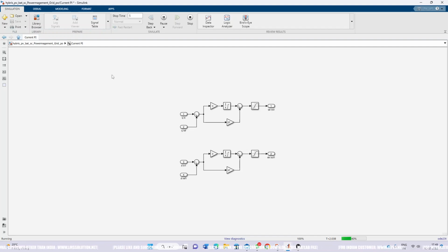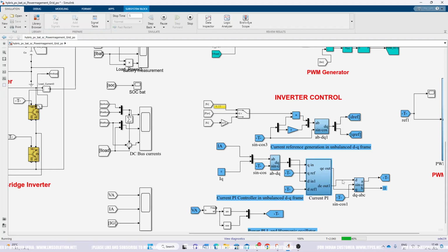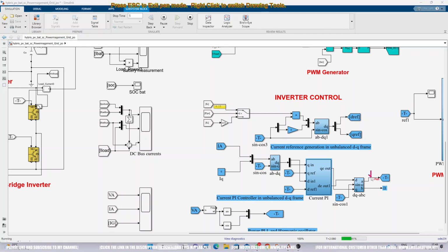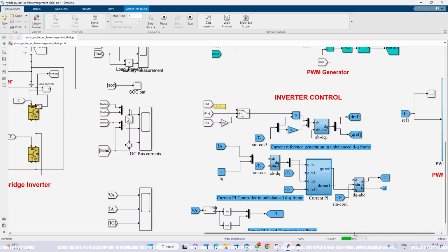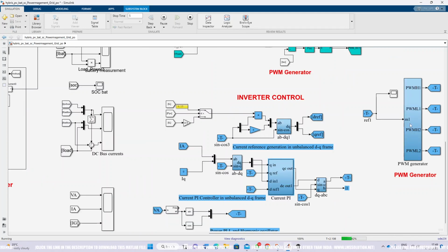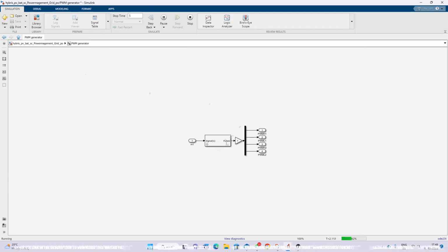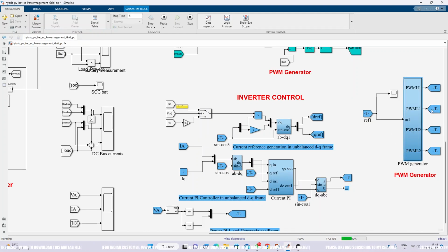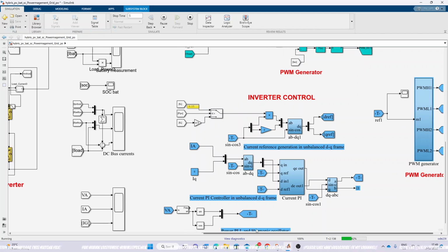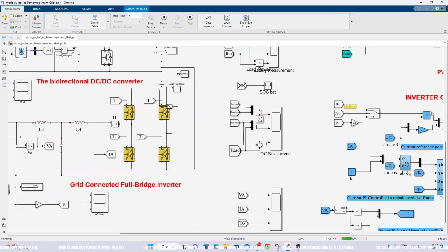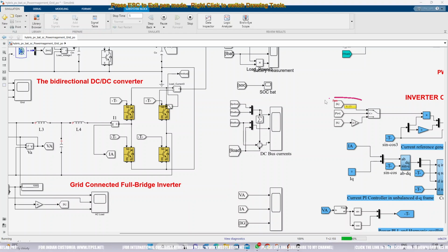The final output of this controller will be in the form of D and Q. The D and Q are converted into alpha-beta form, and then you take only the alpha quantity. This alpha quantity is considered the modulating signal. That modulating signal is processed via this sinusoidal PWM generator, which generates the pulse. This pulse is used to control the inverter based upon this reference current.